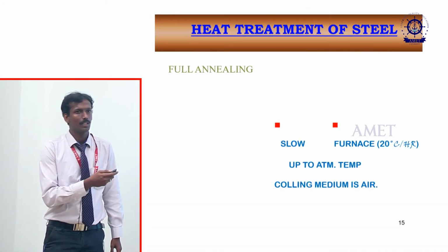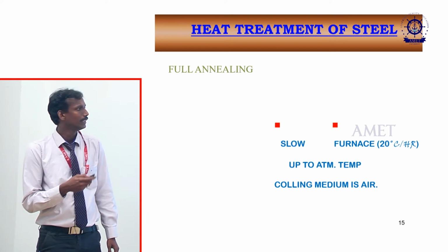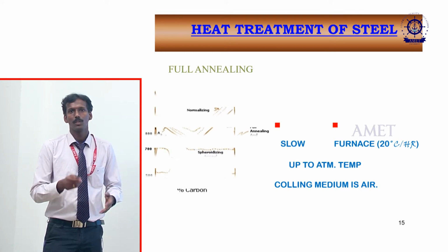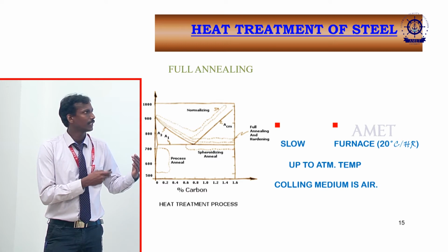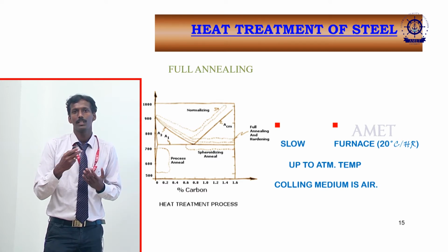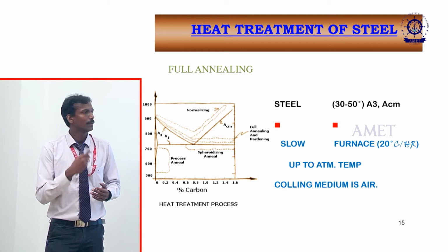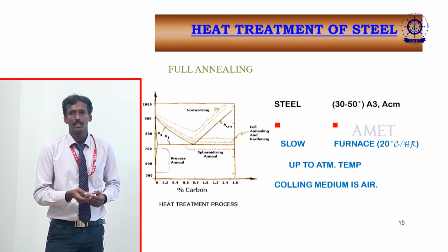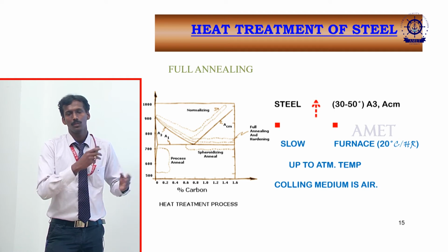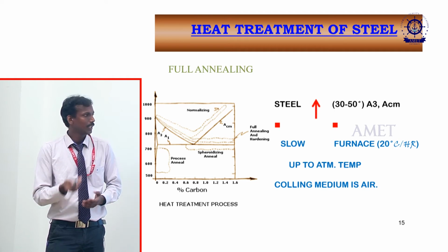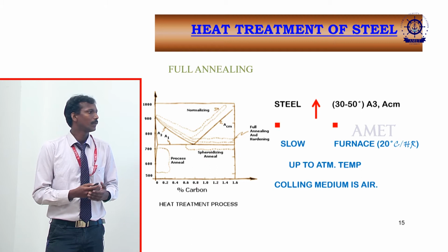So first, you heat above the upper critical temperature and hold it for some time. For example, we could take 1018 steel and heat it to around 925 degrees Celsius. So above the critical temperature you can maintain it, then hold for some time to transform into the austenite stage. Then we can cool down to the lower critical temperature.